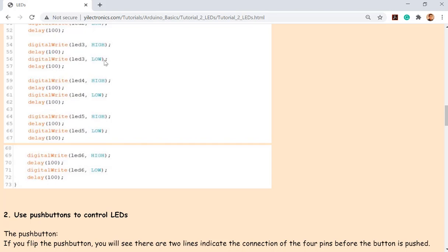But you can imagine there must be a digital circuit inside the device to detect that sequence. Like a state machine. If I receive 1, I'm gonna see if I'm going to receive 0, jump to the other state. If it is 0, then jump to the other state waiting for 1. If it is 1, done. I will start this operation. Otherwise, I'm gonna come back to the initial state waiting for the first 1. It's a state machine, right? Whenever all the states are satisfied, I know I'm receiving a signal. Somebody wants to start a conversation. Then I'll start doing something.